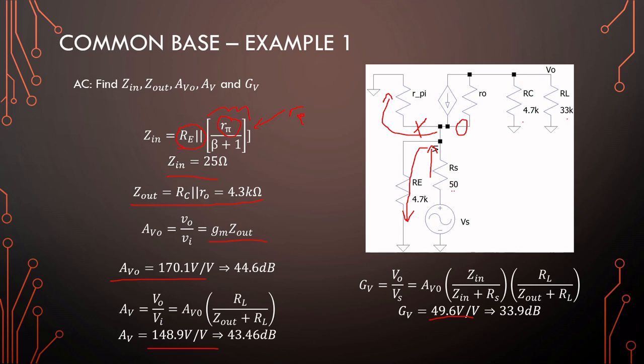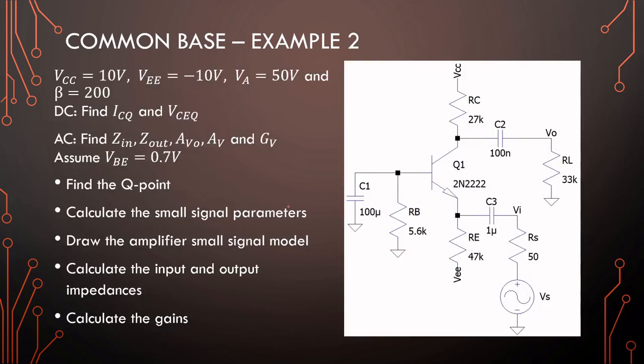So you need to decrease the collector current to actually match this with something. So input impedance is very dependent on the collector current and the choice thereof. The best option for these amplifiers is to actually have a current source to stabilize it. But in any case, moving on, pause and try to do example 2. The only difference here is the biasing and having dual rail.